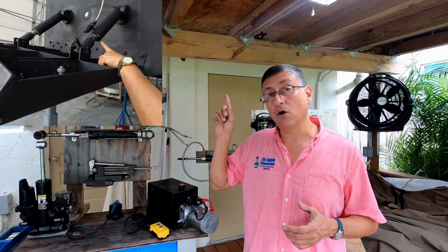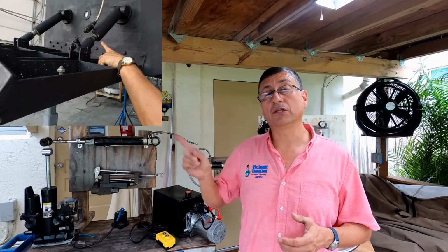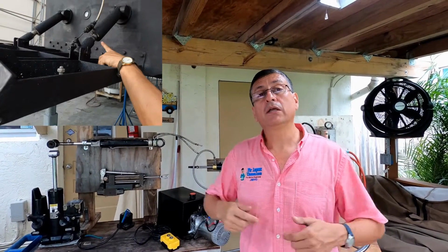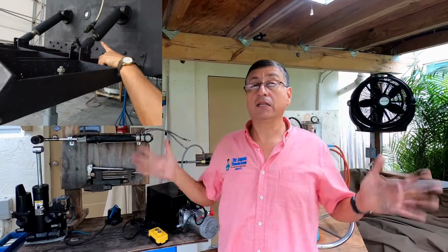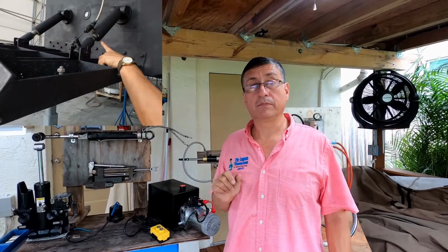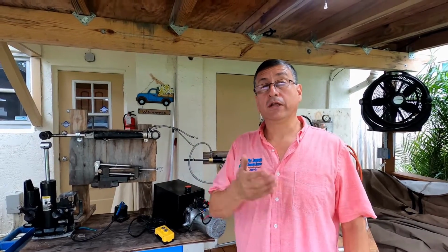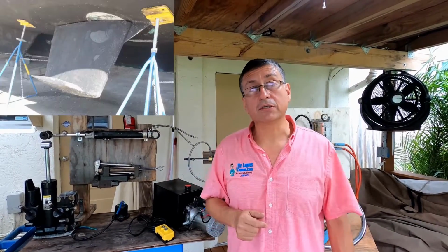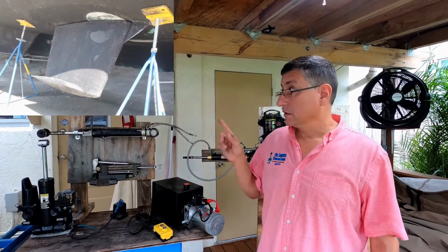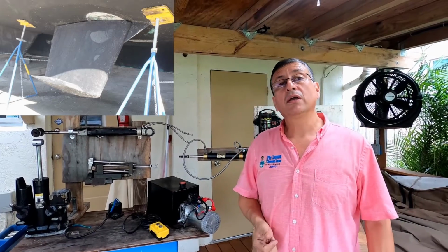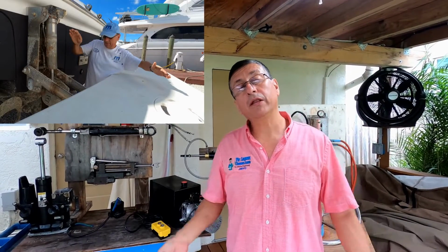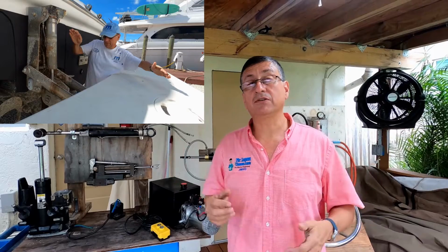If the O-rings, the gaskets on the shaft, on the rod, are broken, the water enters the system and that water contaminates all the hydraulic system, not only the trims. This is one possibility. There are a lot of elements exposed to the water. For example, the stabilizers, the fins of the stabilizer, those actuators are submerged in the water. If the rams have leaks, the water penetrates the system and damages the system.